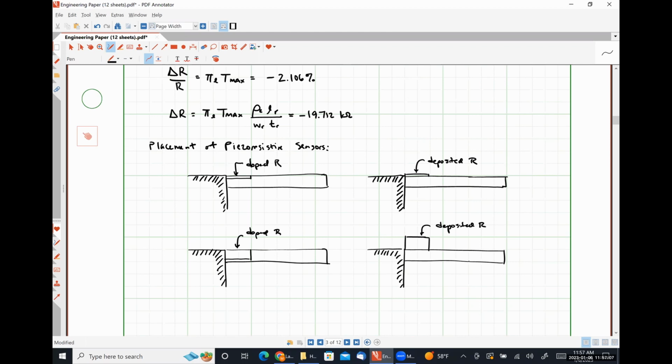So anyway, the first formula of delta R by R, we have delta L by L minus delta A by A. Right. Here we have the area of the... Right, but so if we are dealing with longitudinal stress, should the area change? If effectively our cantilever beam isn't undergoing extension, we shouldn't see that the area matters. Now, if we were dealing with an extension rod thing, that could be a different bag of cats.